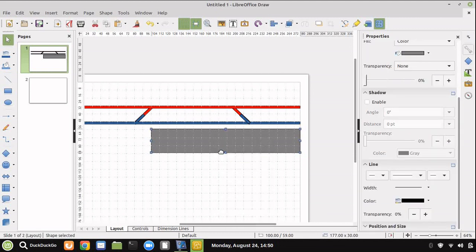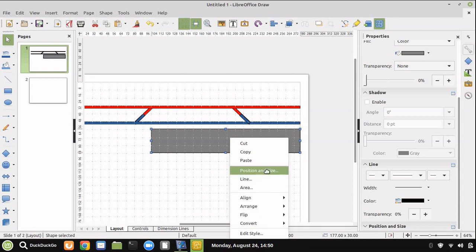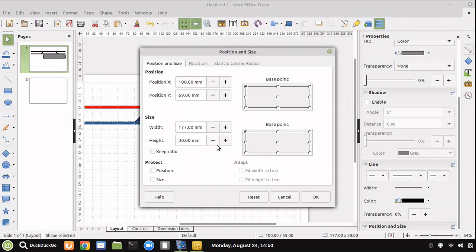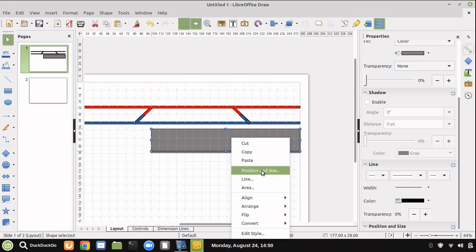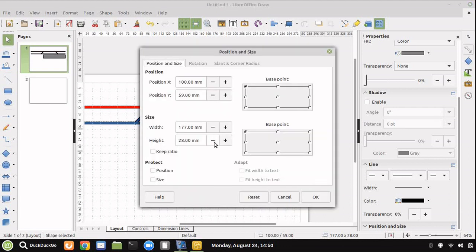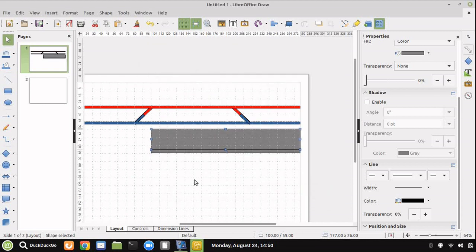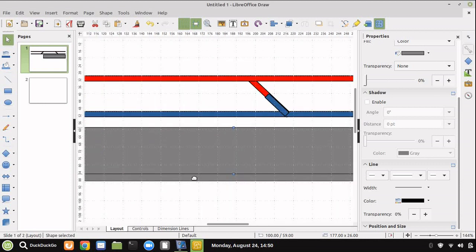So what we're doing here, folks, is we're just changing the colour of the platform there to make it a bit more like a platform colour-wise, and we've copied the original rectangle, and now the second rectangle we're changing the size of it. We're just reducing it a bit. I think it needs a bit more, so we'll reduce that a bit more down to 26 millimeters so that it fits within the other rectangle.